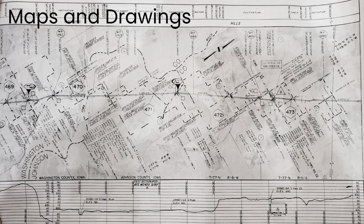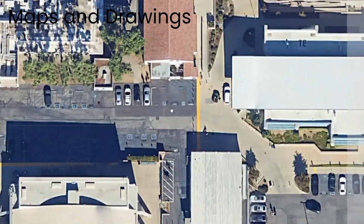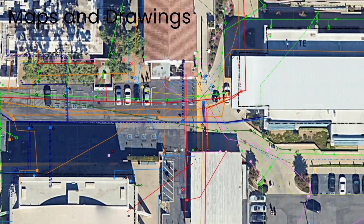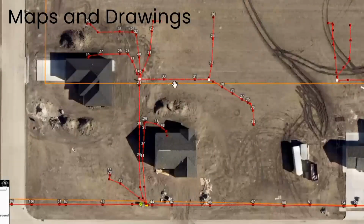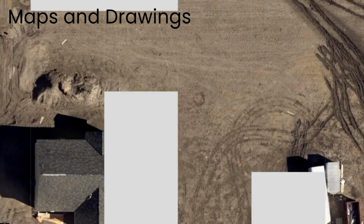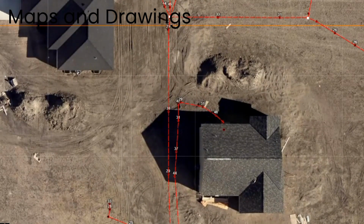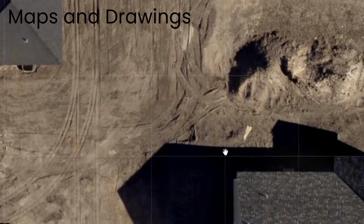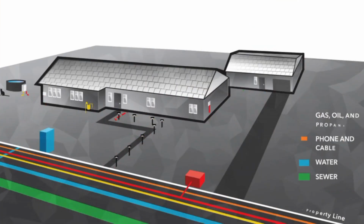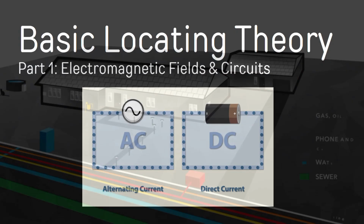So your prints could be paper, they could be as-built, they could be line cards, or they could be a more advanced GIS system. GPS accuracy is getting better, the prices are coming down. We're able to actually use the GIS prints to relocate lines. Here's a nice GIS system with aerial photography in high resolution where we can actually zoom in to the lines that have been installed, the power lines in this case, and we're actually able to see the depth readings as well. You could pretty much relocate just following that line out using a GPS unit with the same kind of accuracy. And so, again, think of it like putting a puzzle together. You start from the outside, you work your way into the middle.